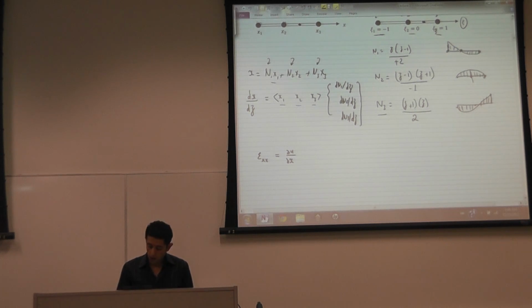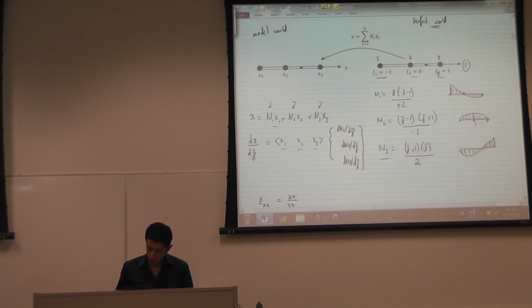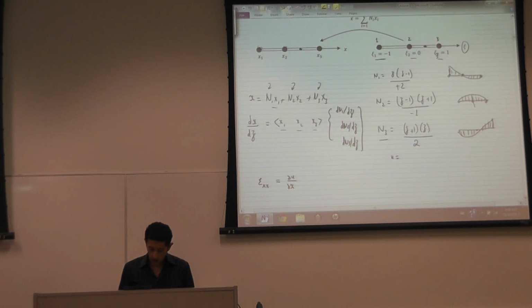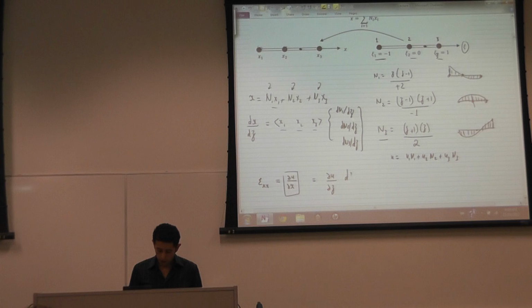But I like to live in my perfect world, so I'm going to write u as u1 n1 plus u2 n2 plus u3 n3, which means I've written u as a function of xc, n, not as a function of x. So how am I going to find partial u by partial x? Well, I'm going to find partial u by partial c, multiply this by dxc by dx. I'm using d instead of partial because we just have one variable here.